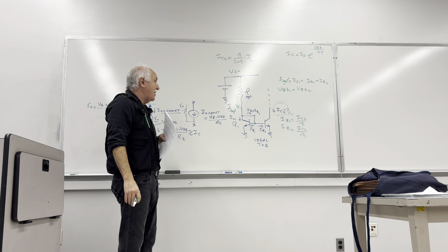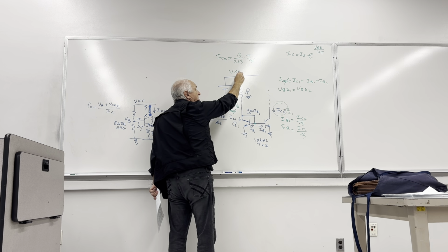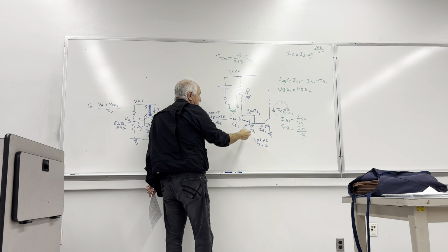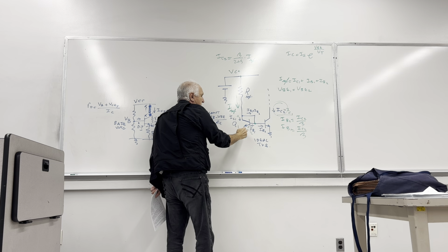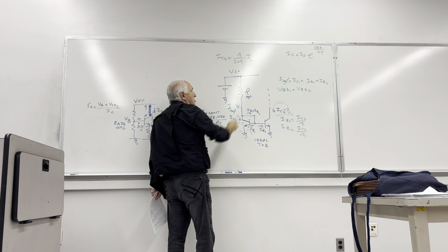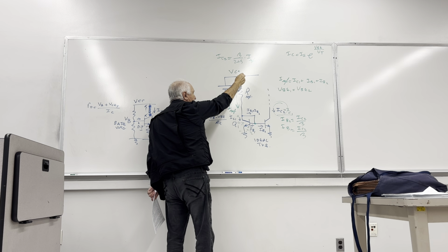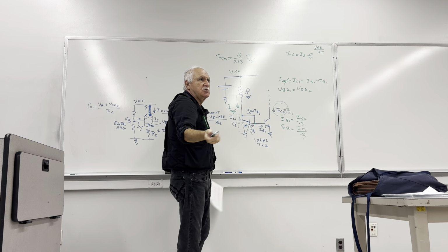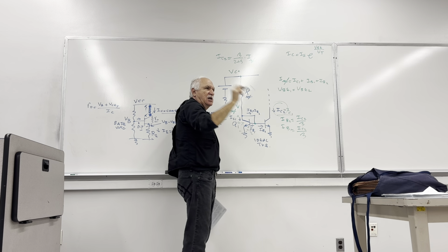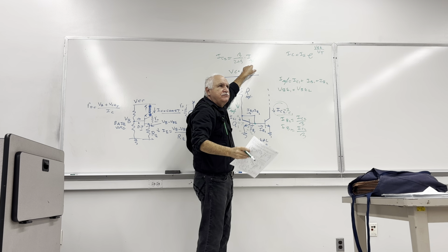It can be easily established. How? Here, whatever voltage is there, 10, 15 volts, this is 0, that's 0.7. So what is remaining on the RF is supply voltage minus 0.7 divided by RF.